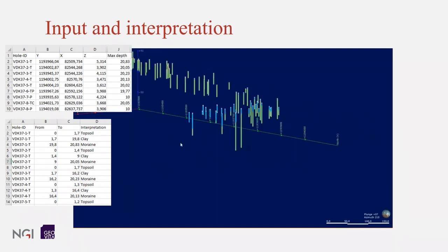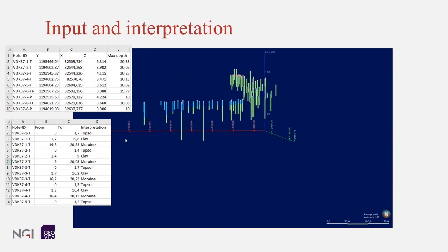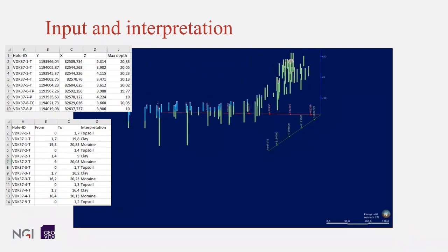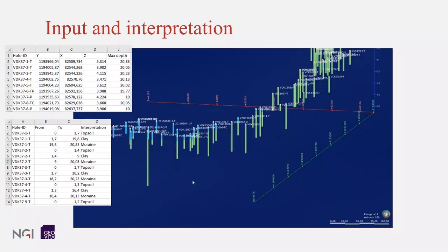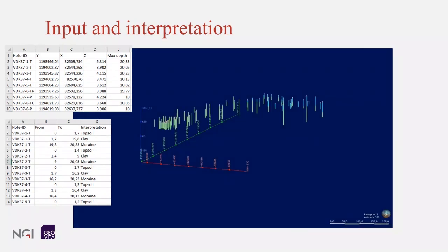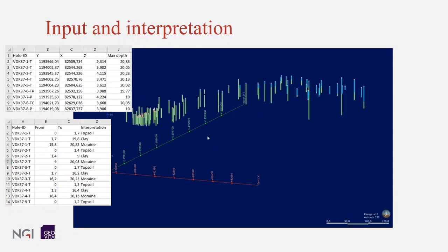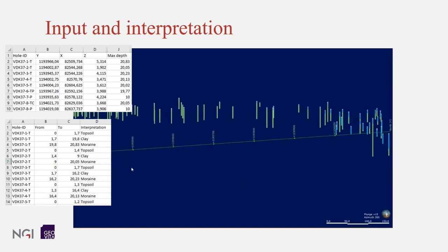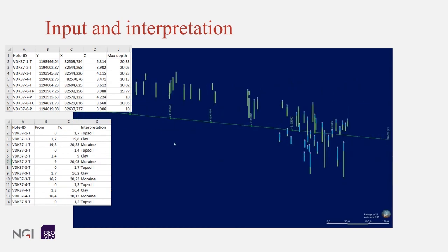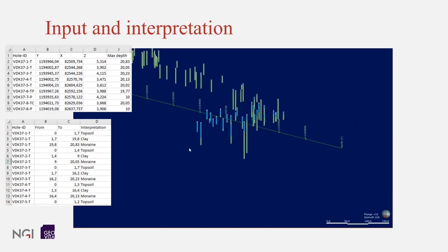For those who don't know total sounding, it is a method that combines rotary pressure sounding with bedrock drilling. But all of these methods have very different levels of uncertainty attached to them. Piston sample is quite certain, while your interpretation of a total sounding is much more uncertain. The 3D visualization is then very good to have so that you can, in some sense, calibrate your interpretation of the soundings based on the samples you have nearby.